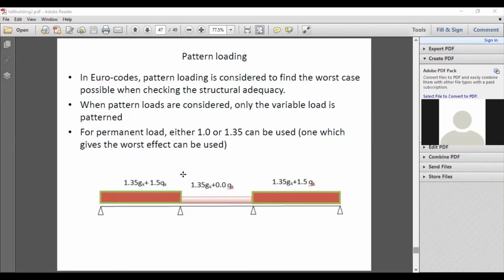And then only you will get the maximum moment here, maximum out of balance moment. And that can be used to calculate the maximum load coming onto the columns. So in addition to that, we can also see that with the minimum load here, the maximum bending moment will occur in this particular span and also in this particular span.